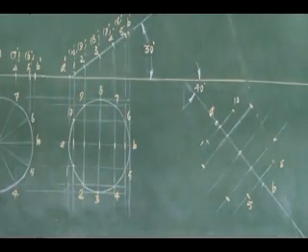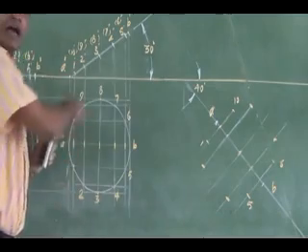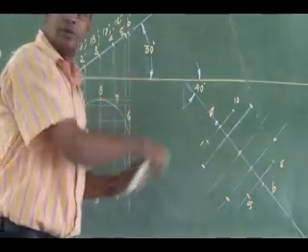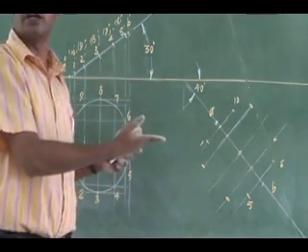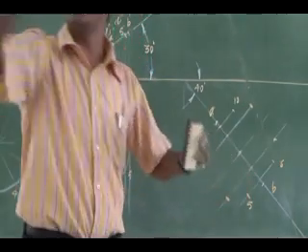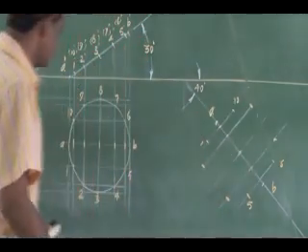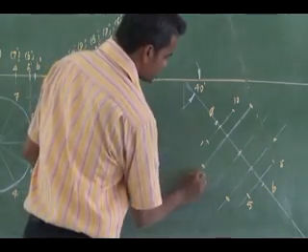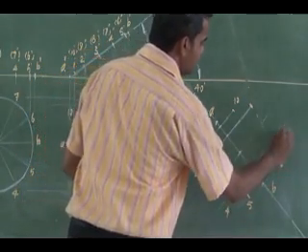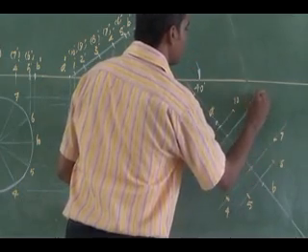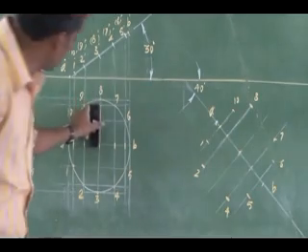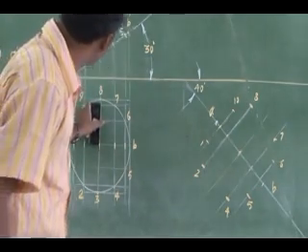Right. So I am getting these points and reproducing this top view here. To reproduce this, as it is I cannot draw it. First of all I have to get these points, then I have to draw the final top view. See here, I have 1, this is 2, 3, 4, 6, 7, 8. Now listen, the distance 8 to 8 I can measure.